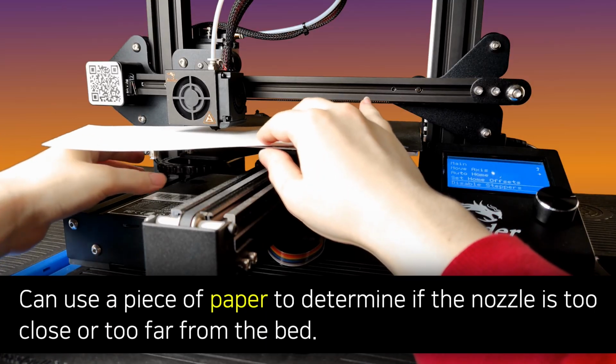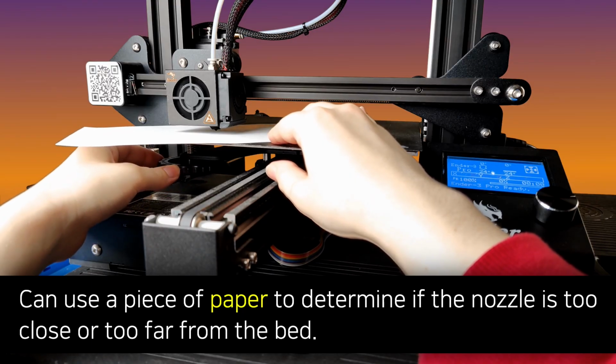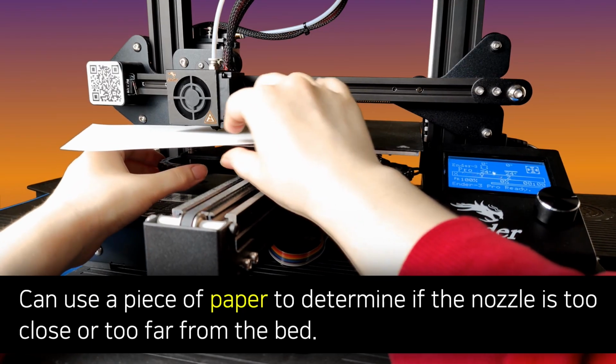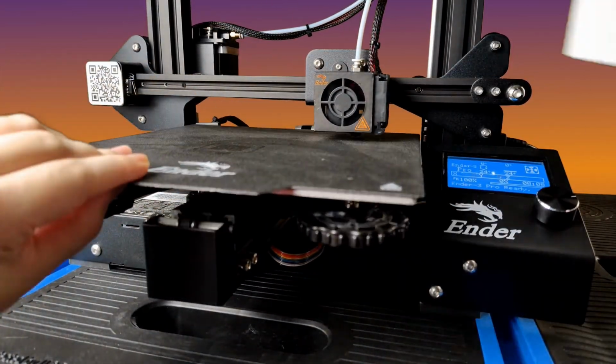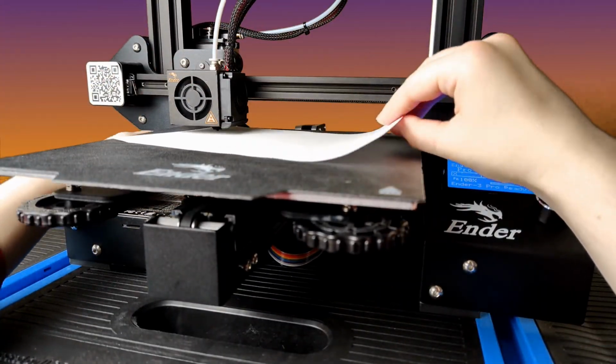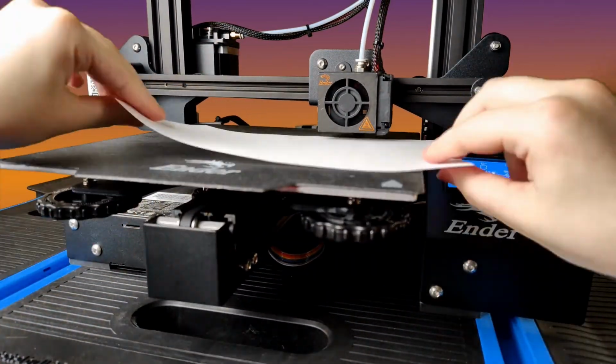Near the four corners of the printer, I am checking and adjusting the level based on the resistance I get from putting a piece of paper between the nozzle and the printer bed. Ideally, I'm trying to make it so that the nozzle is lightly scratching the paper. There shouldn't be too much resistance, but the nozzle should also be touching the paper.